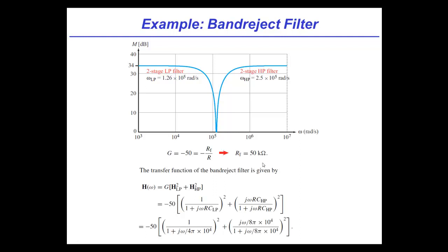As a quick application note, one of the uses of things like this, which are sometimes called notch filters, is basically to isolate out some frequency you really don't want. An example of that is 60 hertz. Why would that be, Michelle? Because it's everywhere, and you don't want it to pollute. And it's everywhere because it's what we use for power transmission. That's right. It's everywhere because it's in your power lines.